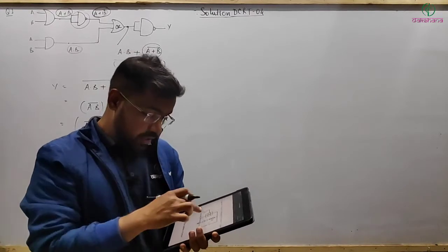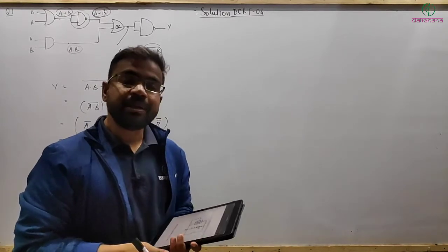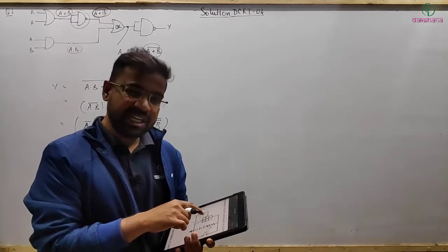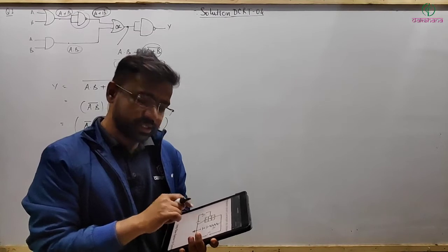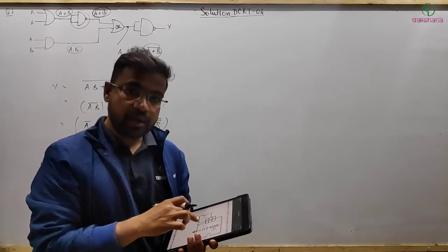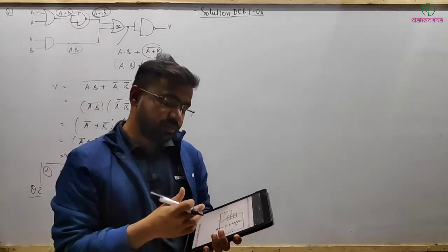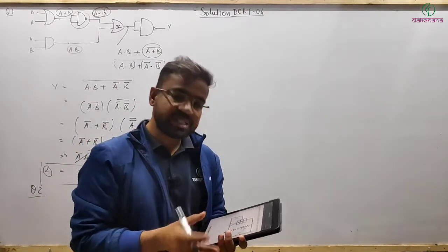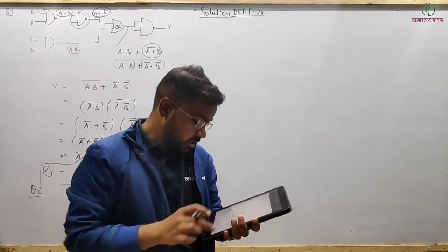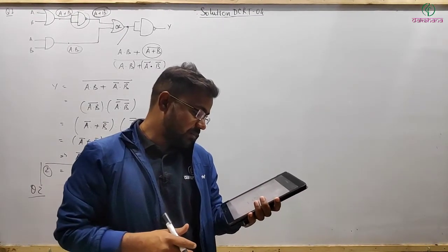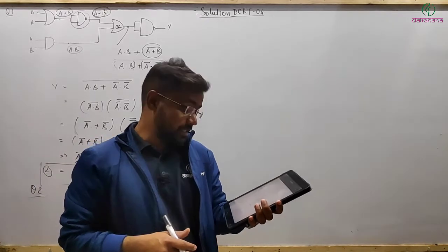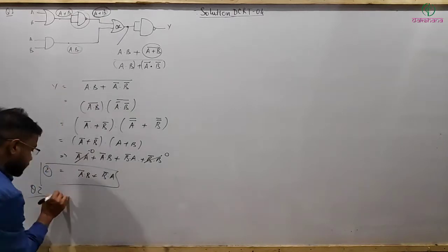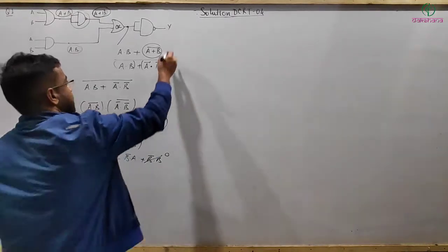Then the lower one can be emitter or collector, but if you look at the biasing, because P type is connected to the positive terminal and N type to the negative, that is forward biasing. So forward biasing is done for the base emitter junction, which means the lower end must be your emitter, and that means it is a common emitter configuration. So a common base amplifier circuit, no. Common collector amplifier circuit, no. The right answer for question number 2 will be common emitter amplifier circuit.